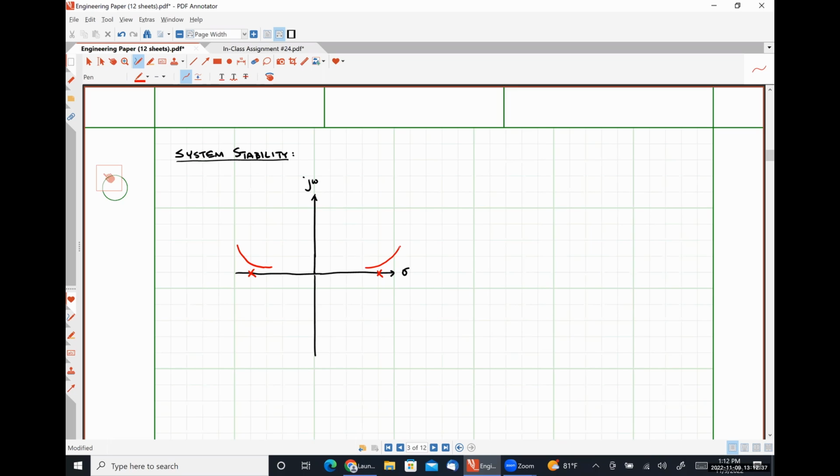Now, an exponentially growing signal mathematically will never reach a maximum value. In a practical system, specifically an electronic system, it's going to go towards the power supply voltage. Okay, so effectively it's going to swing towards VCC plus or ground in our systems because we've designed a single supply op amp. But if we had chosen instead of ground VCC minus, it would swing towards that depending on the conditions. All right. We could also have the case where we have complex conjugate imaginary poles.